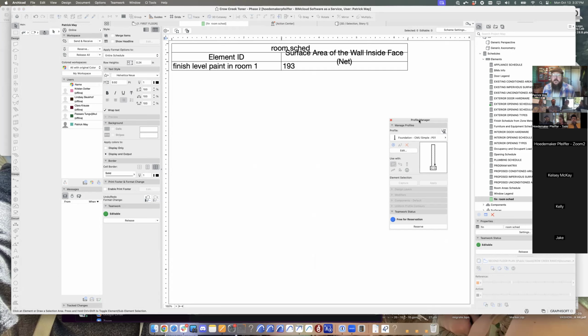And the other way to do it, another question I have is, okay, let's say that I don't care about the efficiency of having fewer wall types, but I do care about the ability to schedule all my interior surfaces correctly without having to manually do it. Could I create a wall type for every condition with every different surface and do it that way? Absolutely.